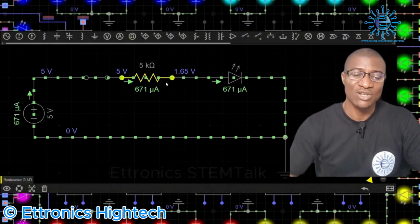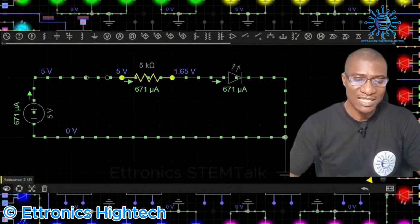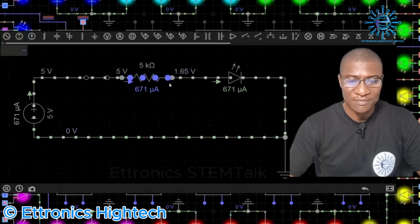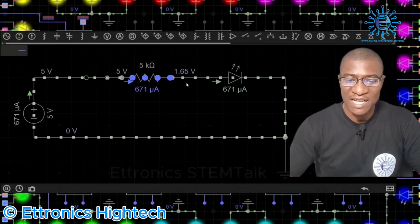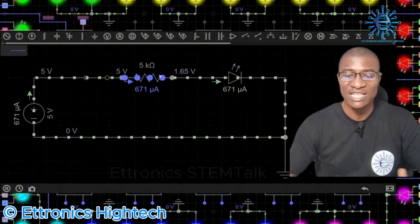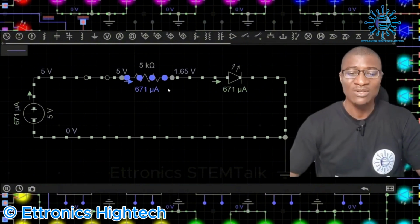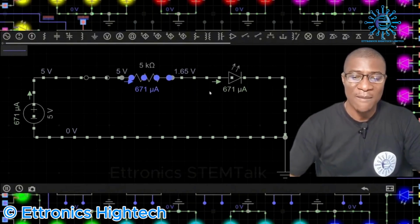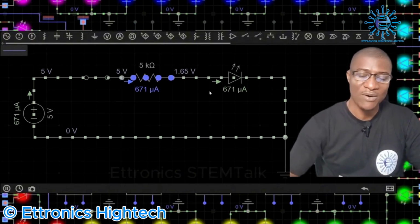So when you are selecting your components, you should be able to select the components with the appropriate values. If you select components with the wrong values, you will not get your desired result. Here, the current has been reduced to 671 microamperes, and it is not enough to power the LED.